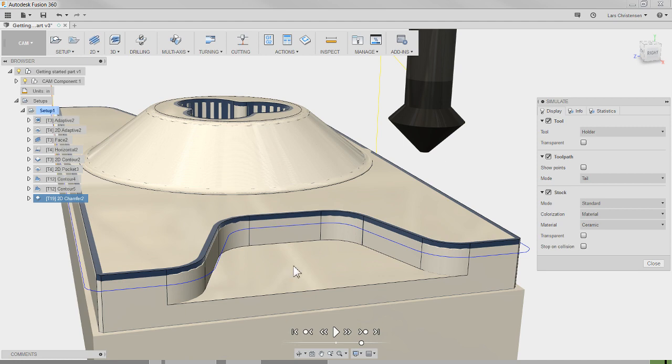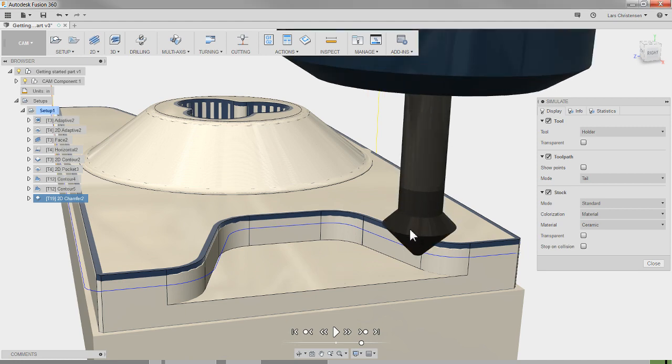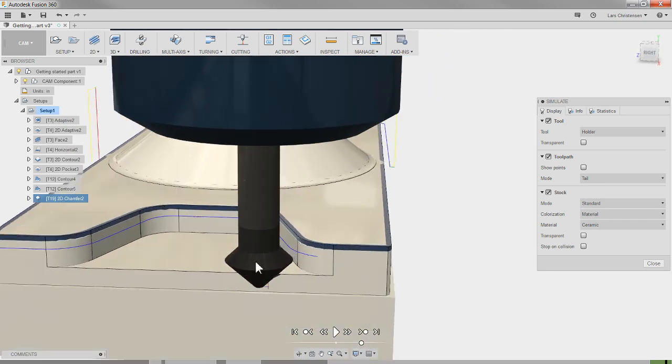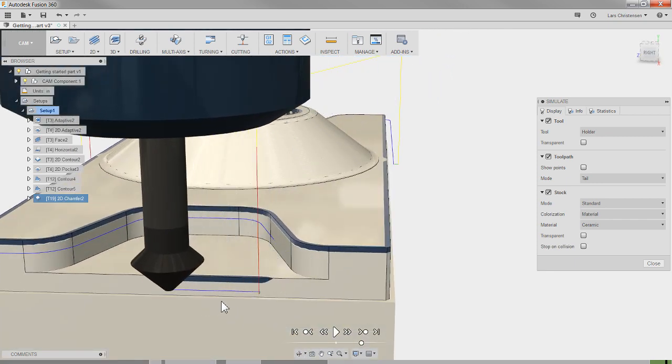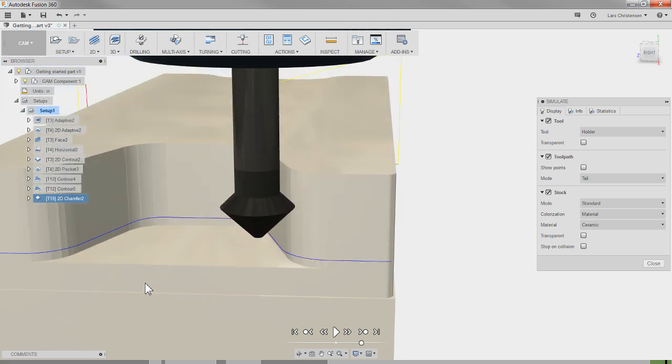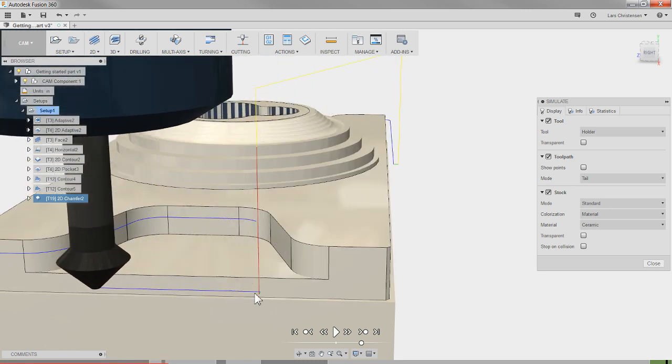It's smart enough to know the cutter diameter and not hit with it, so it cuts it short, and the chamfer starts only where it can go. See that? So it comes right down there, so it never hits that wall. What is absolutely awesome with that toolpath.